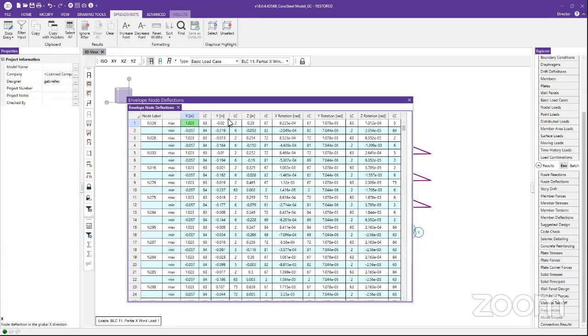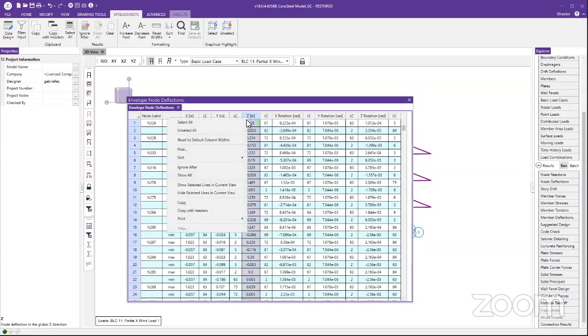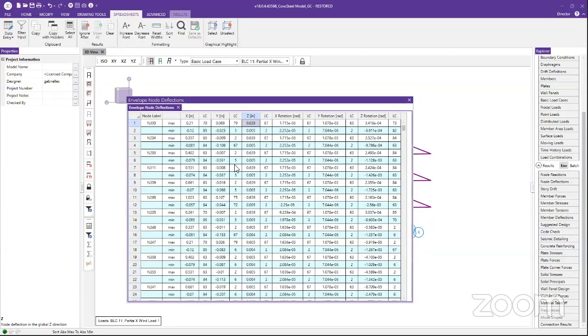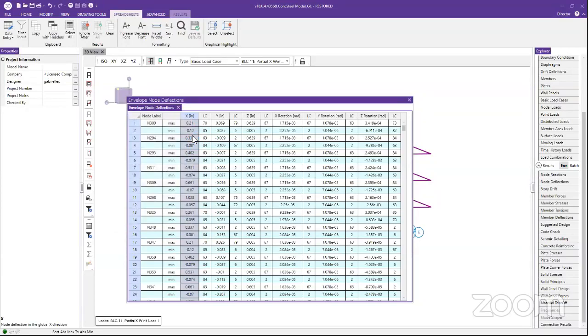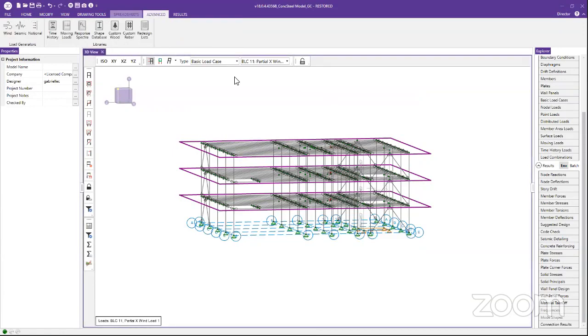That makes sense to me. So that's kind of in the ballpark of what I would think. I would then also do a Z direction, and I'm also noting what the load combinations that are governing are, the ones that we're worried about. So I can take a look and say, okay, in that X direction, that was load combination 63. That was one of concern, maybe if it's 1 inch of deflection, the worst case of deflection. So then I would walk down the path and start to see what's happening in that.